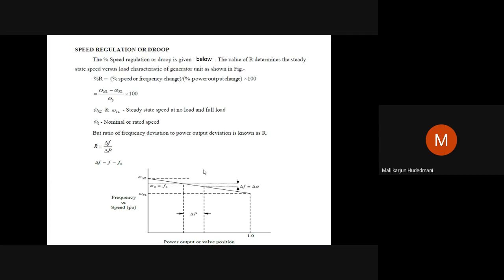As and when a fall of frequency is noticed, we call it falling. There could be a controlling action on the controller that will adjust the input point so that the error is brought back to zero. This is how the fall of frequency or RPM is taken as an input stimulus for the controller to shift it back to steady state RPM or frequency.